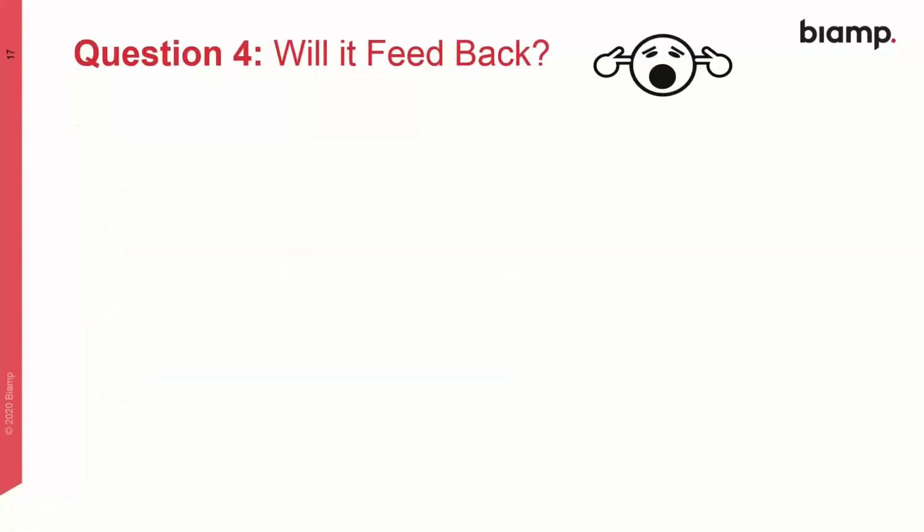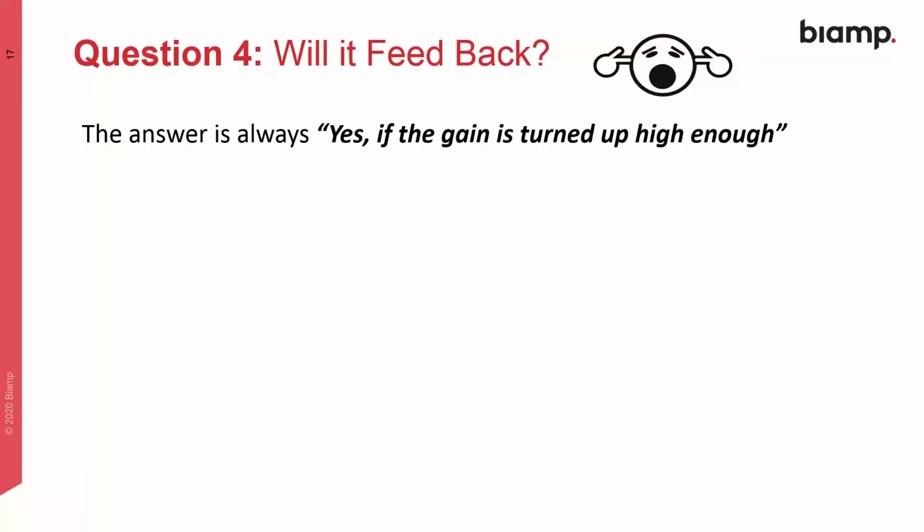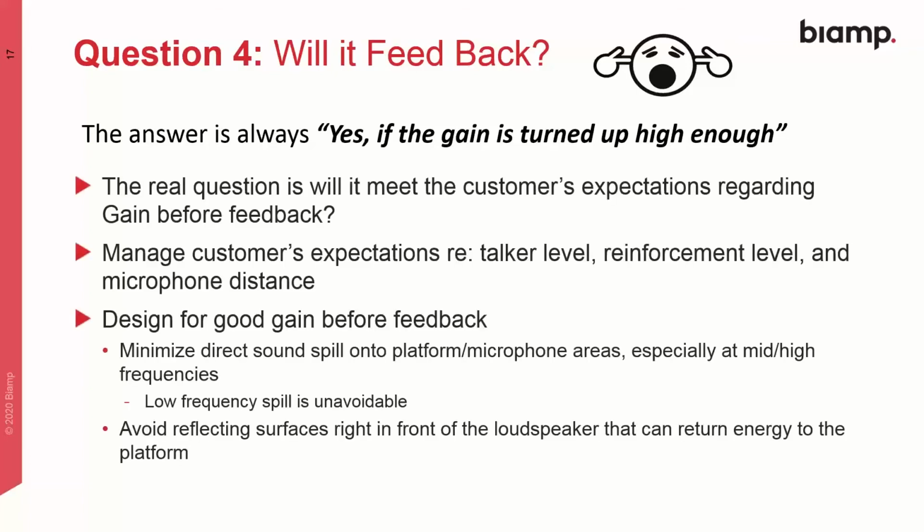Question 4, will it feed back? The answer is always the same. Yes, if the gain is turned up high enough, it will always feed back. The real question is, will it meet the customer's expectations regarding gain before feedback? You need to manage the customer's expectations a little bit regarding talker level, reinforcement level, and microphone operating distance.